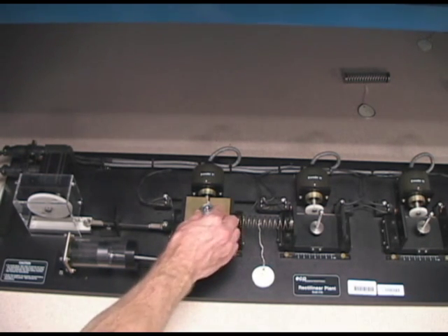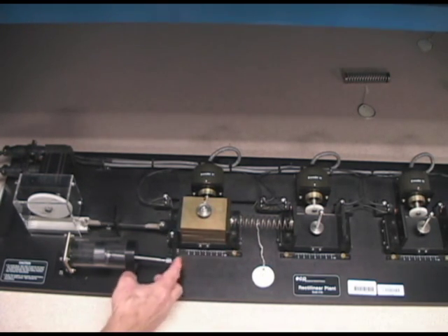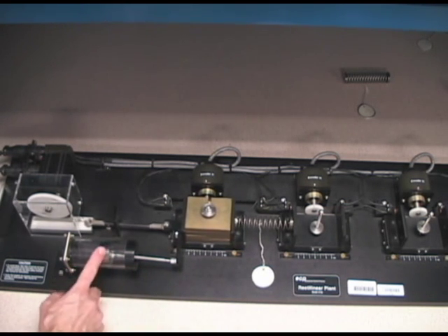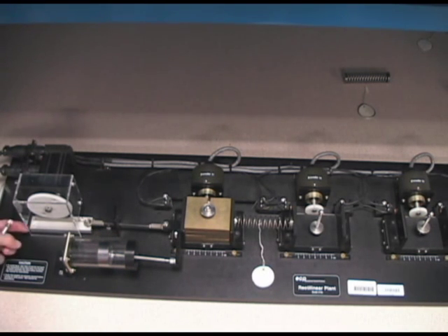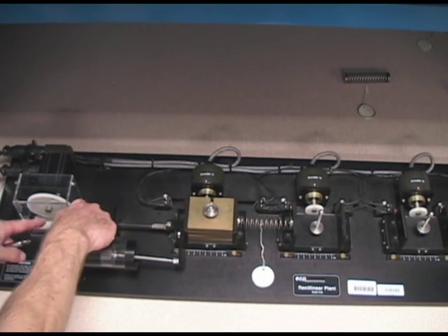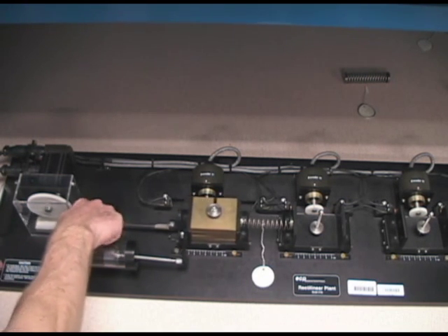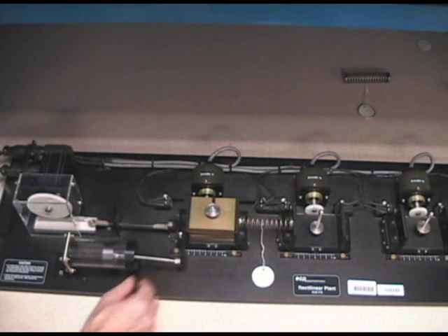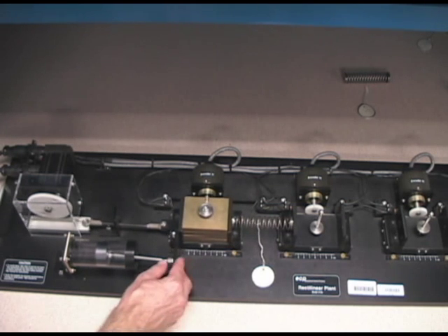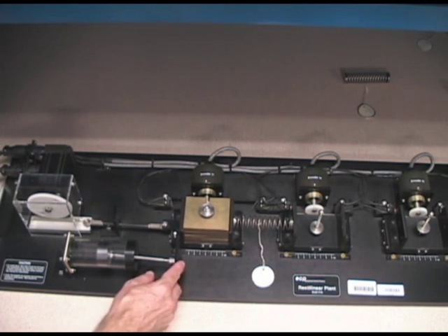You'll need to thumb that down tight, and then this is the dash pot, which you will be measuring in terms of the B coefficient subsequently in the lab. Here is where the force will be applied through this rack and pinion mechanism, and what we want to do now is go through the equations that will tell us what's actually going to happen in our system.